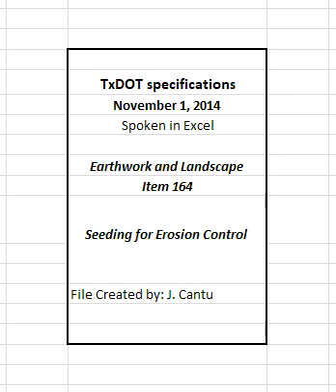2. Materials. 2.1 Seed. Provide seed from the previous season's crop meeting the requirements of the Texas seed law, including the testing and labeling for pure live seed, PLS equals purity times germination. Furnish seed of the designated species, in labeled unopened bags or containers to the engineer before planting. Use within 12 months from the date of the analysis.